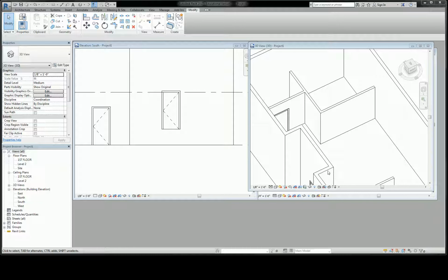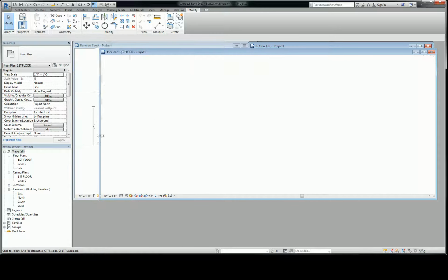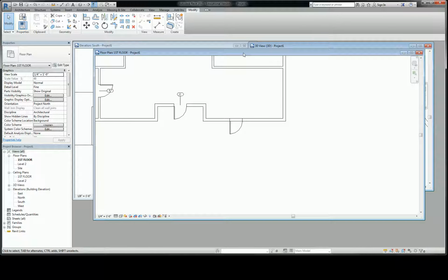We're going to get into plan view for this one. So the way that a lot of elements work in Revit. Okay, so this is your first time building a profile-based family. A floor is really nothing more than the extents of a profile of like a pad, right? If you pour concrete, you're going to put like 2x8s or whatever around the whole perimeter of it, and then you're just going to pour the concrete and it'll go flat like a pancake. So really what we're doing is we're drawing the boundary of where the floor is. Duh.